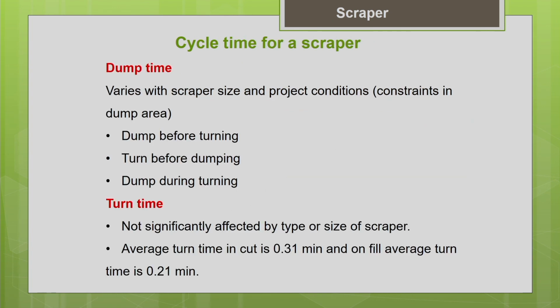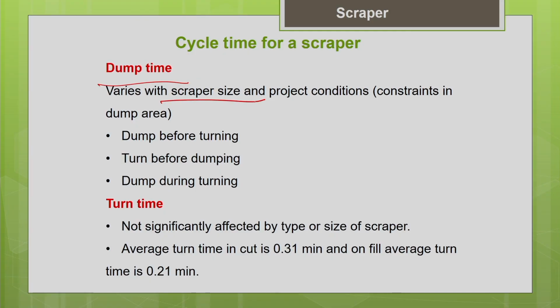So the next important thing which we are going to see as a component of your cycle time is your dump time. Your dump time of your scraper depends upon your scraper size. Obviously, the bigger the scraper, your dumping time will be more. It depends upon the scraper size as well as the material which it is handling. If it is a loose, free-flowing material, it will be very easy for the scraper to dump it. If it is a very cohesive, sticky material, in that case dumping time will be more.